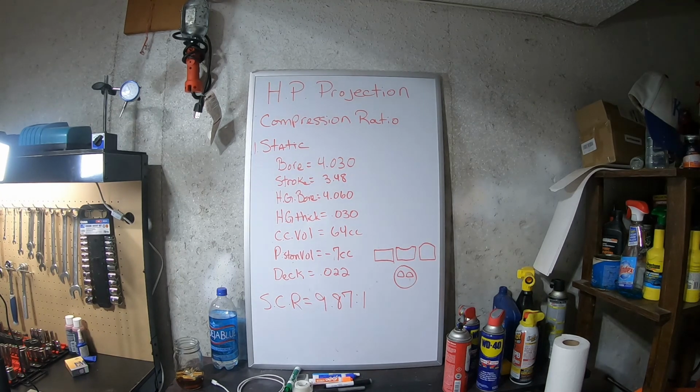And this motor really, I don't want it making more than like 450 horsepower. I don't think I'm going to get close to that, but that's about as much as I'd want to put into a 2-bolt main Chevy. And the internal rotating assembly components are rated only to 500 horsepower. So I want to keep it safe. So we're going to give it some space, let's just say, compensation for power.